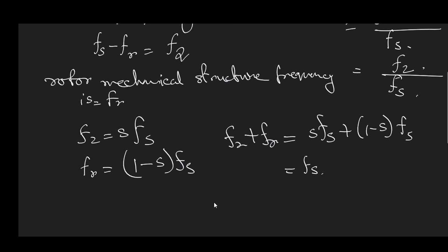Although the rotor current or rotor induced EMF has frequency F2, or S Fs, with respect to the rotor rotating structure, with respect to a standstill reference frame it is Fs, which is the same as the supply side or stator current or voltage frequency.